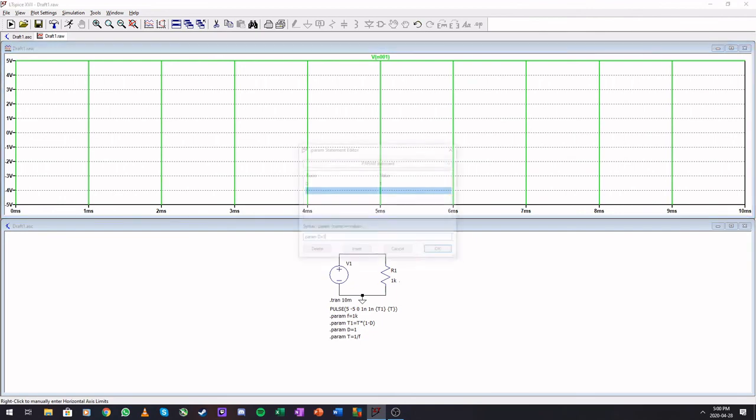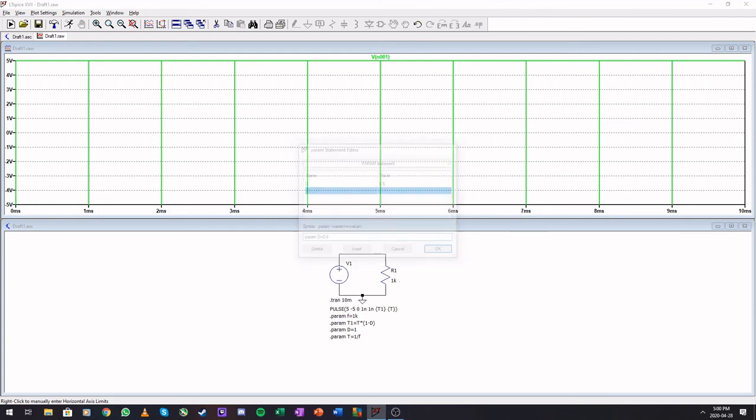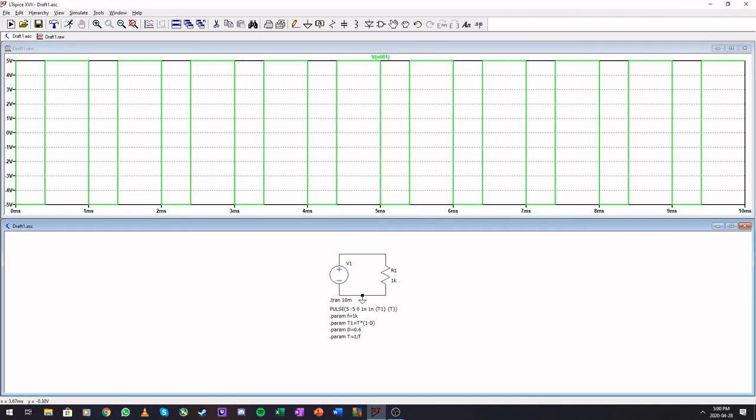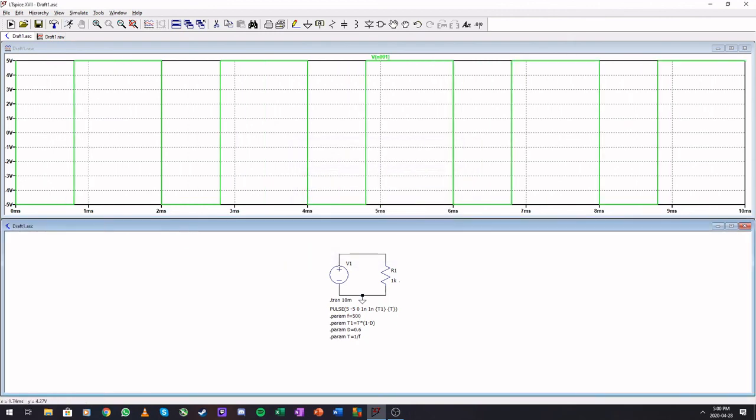This should be nice for people that want to test systems where you have different duty cycles and want to do them one by one on different ratios. So you can build your duty cycle, set the duty, set the frequency, without having to go and adjust this pulse parameter continuously and having to remember what value do I need to manipulate now.